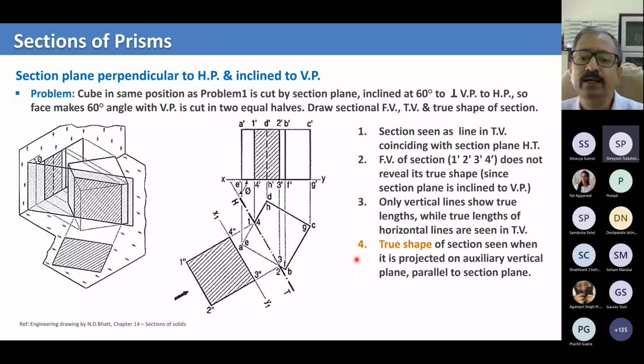Okay, and of course we have a little bit of choice of the distance between the cross hatching. But make sure that it is not too fine, that is more trouble for you, nor too far away so it doesn't look like a cross section. So there will be some balance of the distance between the cross hatching lines, right? I think if you go back to the book, there may be some rules of how far apart it should be. Anyone tell any rule about how much distance between the cross hatching lines?